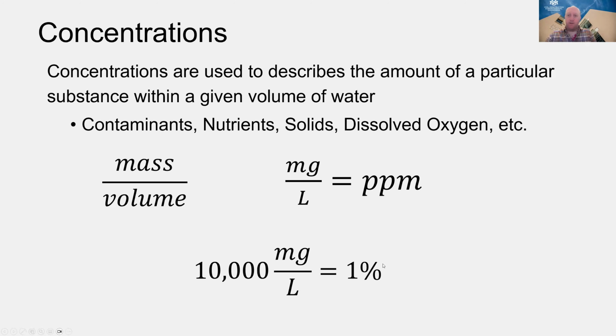A lot of times you'll see percent in chemicals. Chlorine's a good example. Sodium hypochlorite is usually about 12 to 13%. So that's like 12% of that solution is chlorine, where the other 88% is just water. That 12% is the chlorine that's actually going to do stuff. So you have to take that into account when you're adding a chemical to anything, because a lot of the times it's not completely pure. It's in a solution with water already.